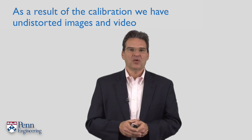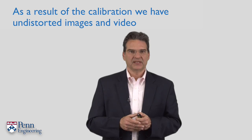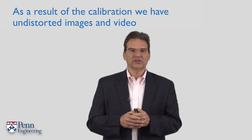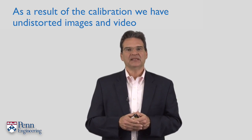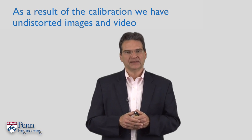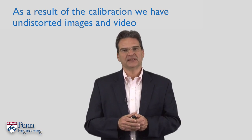Let's see now how exactly we perform this calibration. To perform this calibration, we need to compute the intrinsic and extrinsic parameters given world coordinates of some points in the world and the corresponding coordinates in images.